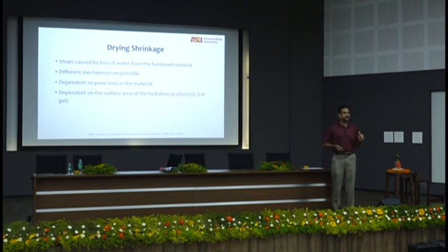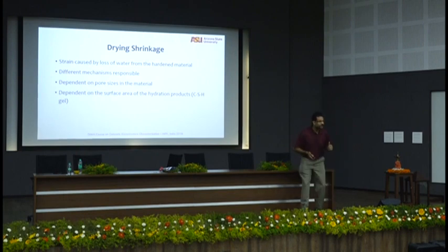So, now let me ask you a question. What test do you use to measure shrinkage? How do you measure shrinkage? Take a bar, put in 2 studs at the end and measure the length, right? You are just measuring what? Free shrinkage strain. Will that concrete that you are measuring the volume ever crack? If that doesn't crack, why am I bothered about volume change? And is that volume change the right volume change when something is restrained? Again, a wrong test, bad test.